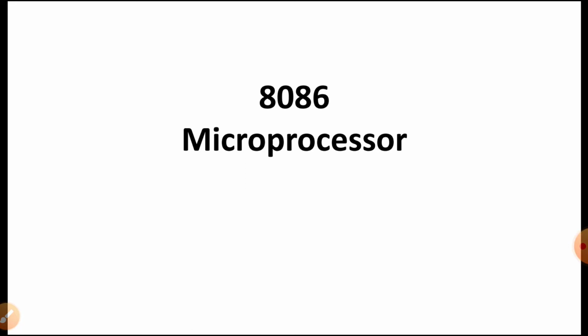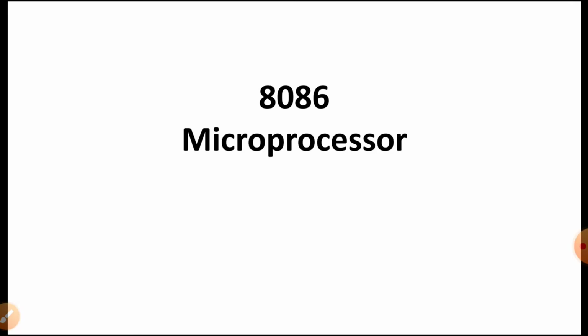The second limitation was that the instructions are made up of 8 bits. So, the maximum number of instructions available is 2 to the power 8, that is 256. It means only 256 binary patterns can be used for the individual instructions, and that is why you have seen that in 8085 you do not have any instruction by which you can do multiplication as well as division.